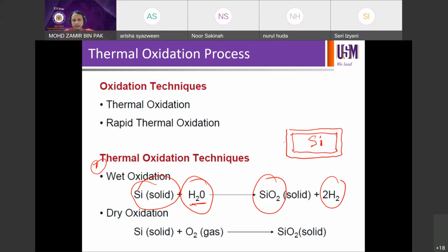When you put it in the furnace, it will cover oxide all around the wafer, because you have silicon everywhere, right? Silicon on the top, silicon at the bottom, silicon on the side, everywhere silicon. So since silicon is the source of the growth process, you're going to have silicon dioxide literally everywhere. Okay, so that's process number 1.